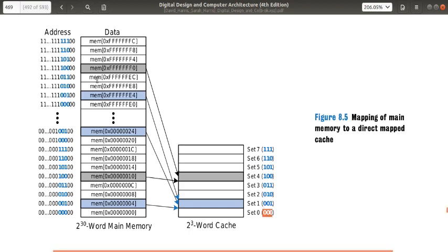So if you look here, this is the address. Even though we are using word addressing, the address given here is the byte address, right? So the last 2 bits are always 0, because each word is given, and a 4 byte jump is there. So let's forget about this. The next 3 bits are where the change is happening, right? The next 3 bits, that is given in blue here.